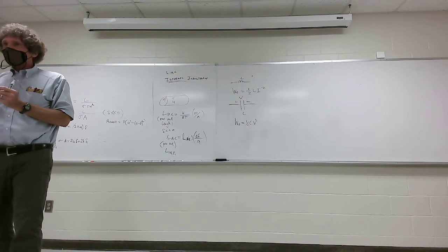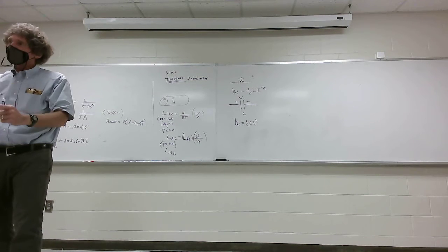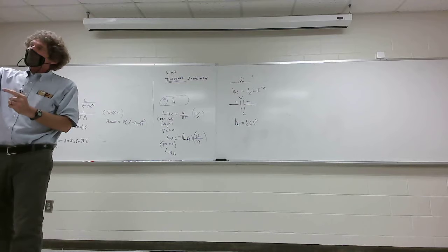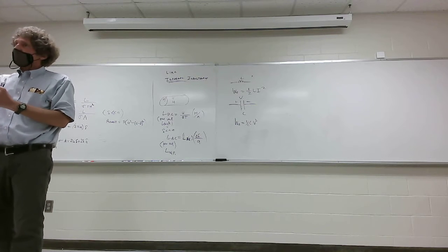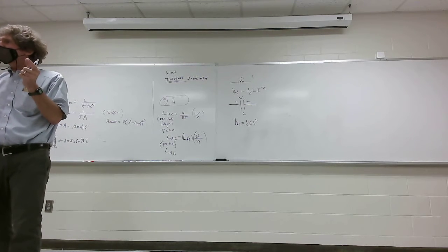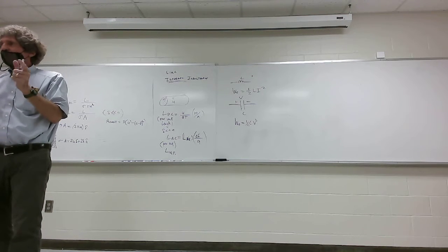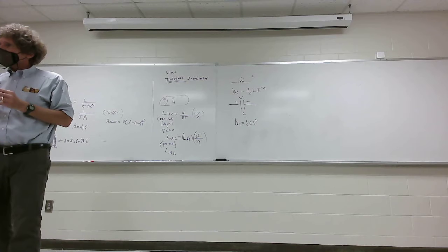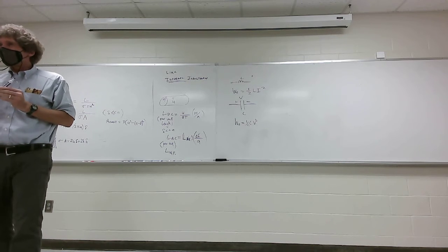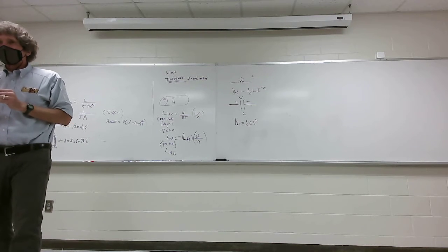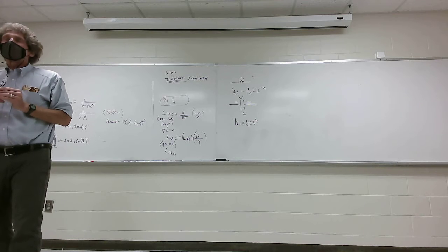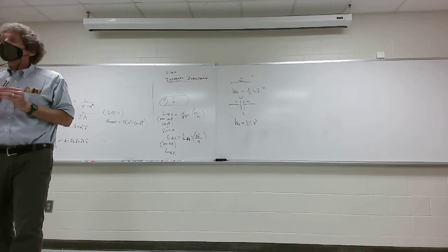So we needed this inductor, and they used hollow PVC with large 4-aught cable that they wound, and they used Bondo to hold it down. Y'all know what I'm talking about? Fiberglass, that stuff you fix your cars with, and boats. Well, then somebody thought, hey, that's an enormous magnetic field in the center there, and that would induce a current on a conducting can.